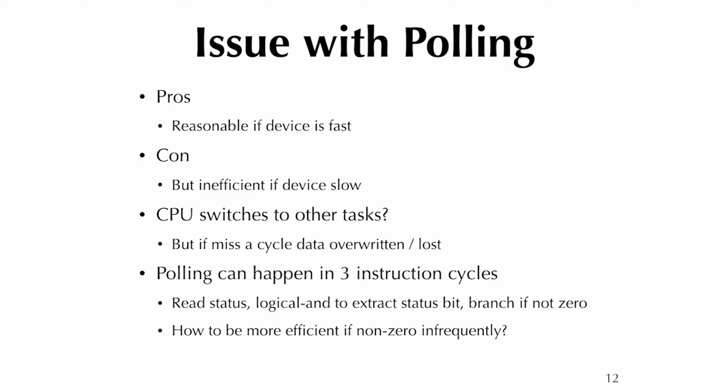So yes, it takes a long time for a byte to be shifted in, but if you wait too long, another byte already comes in, and you're still doing your useful work. You think you're trying to utilize your processor, but in the meantime, that new byte overwrites your old byte. Okay, and so by the time you come back and check again, well, you already lost a byte, if not more. Okay, so you have that dangerous losing event.